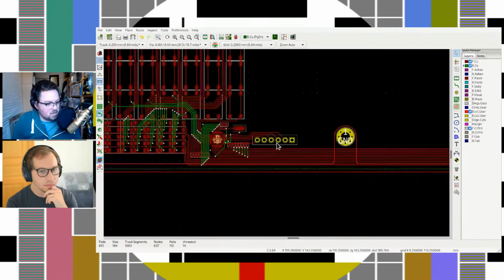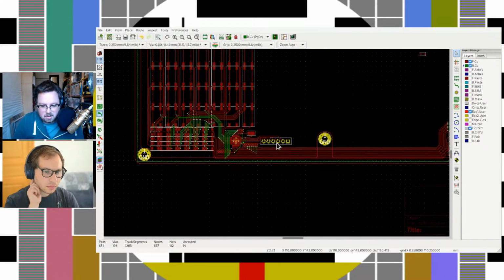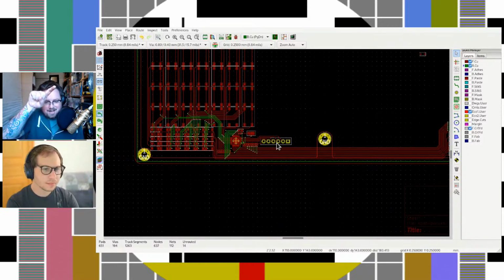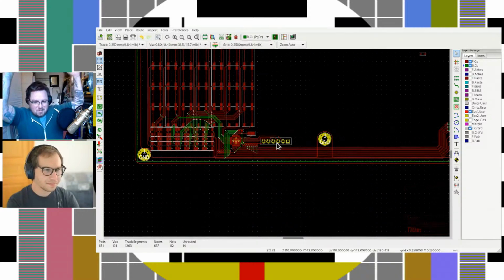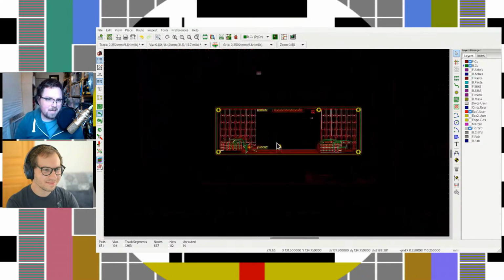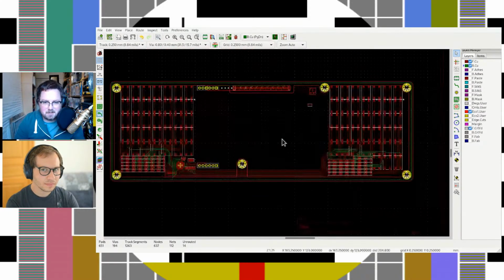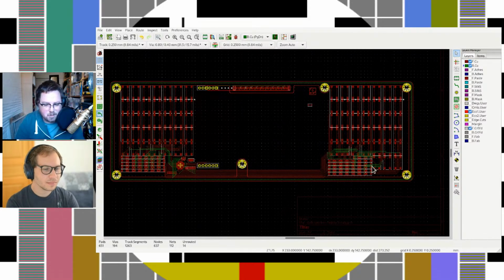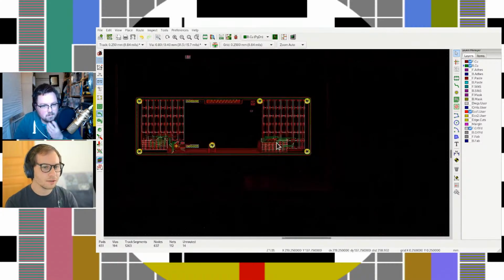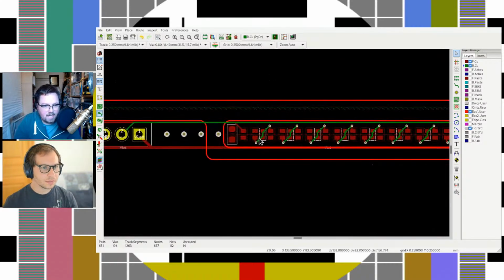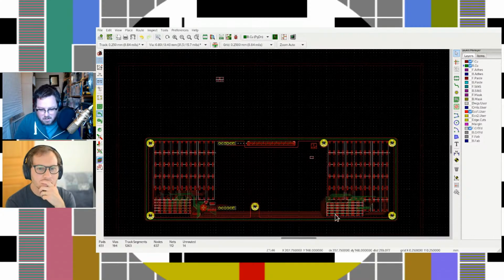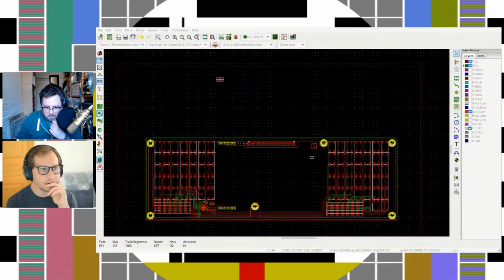And so then if you're just using an off-the-shelf microcontroller, you can just go, all right, well, I'll just make a little socket for the microcontroller on a board, and then I'll run 2 wires over. Yay, it was simple, and maybe I can make the keyboard stuff expensive 4-layer, and then the little microcontroller adapter board is just a 2-layer or something like that. Right. I also have some stuff like LEDs up here, but I don't have LEDs under the individual keys.